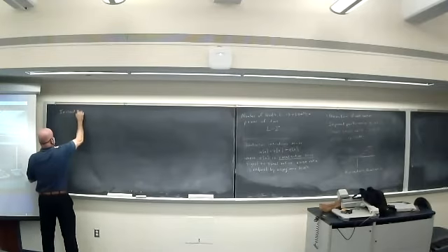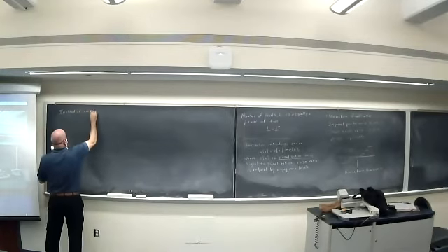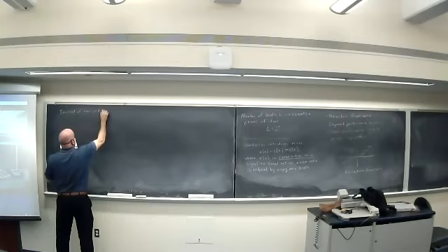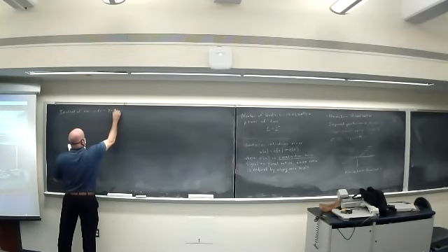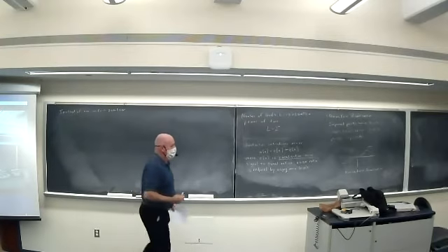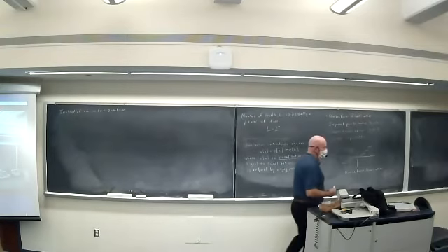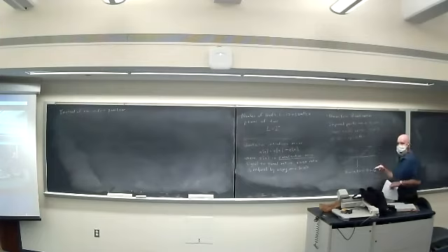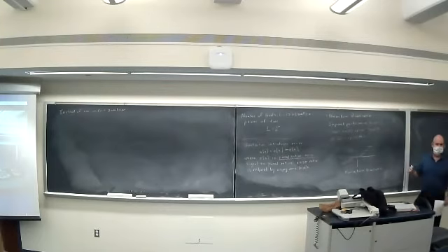Instead of a non-uniform quantizer, we can equivalently, we talked about this, I think, last time, amplify my low volume signals, make them bigger, and perhaps attenuate the higher amplitude signals, deliberately distort the signal, and run it through a uniform quantizer, and get the same effect as non-uniform quantization.